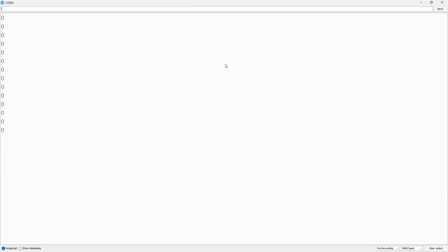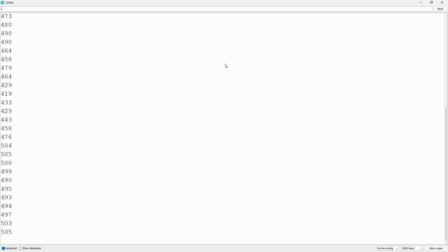We'll start off with the analog input. When the water level is at the highest, the ADC input, the analog input, is not 1023. Because I'm going to do it in percentages, I'm going to have to use the maximum or mean ADC analog input value that gets read. This will be more evident as we go through the code.